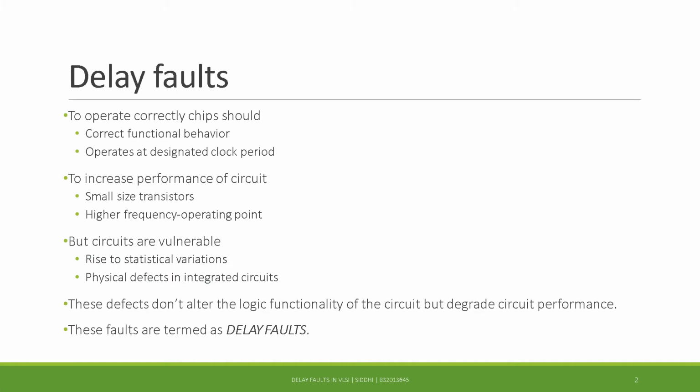Delay faults. Nowadays, transistor size is shrinking and logic circuits are operating at higher frequency to increase performance. For manufactured circuits to operate correctly, it is essential that the circuit has correct functional behavior and operates at the designated clock period. But due to the shrinking transistor size and high operating frequency of logic circuits, the manufactured circuits are more vulnerable to the manufacturing process, which gives rise to statistical variations of the parameters and to some extent